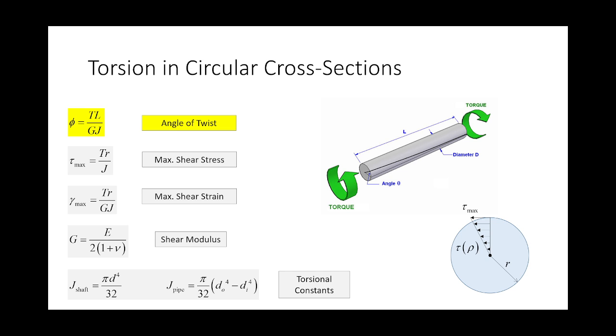They are, and not only are they really similar, but let's look at the parameters. So we have up top a member length, a member length. What's the next term? This is applied load. This is applied torque. So some external force or demand being applied to the system. What's on the bottom? Here we have E, here we have G. Both of those are material properties. Now what about the other ones? A and J. Those are section properties.